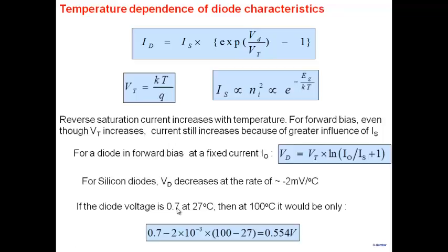Where does that heat have to go? It has to go towards the ambient. The heat has to be released to the ambient. Now, you can realize if the ambient is 50 degrees and I have a source of heat, there's a thermal resistance between the ambient and the source of the heat. So what happens is the junction temperature can be significantly higher than the ambient temperature.